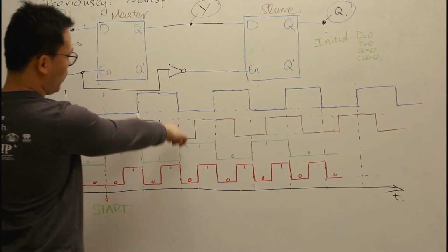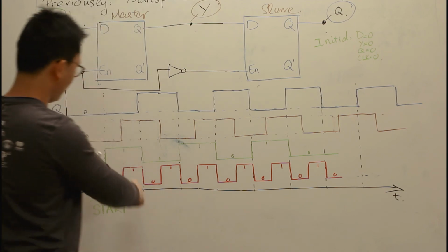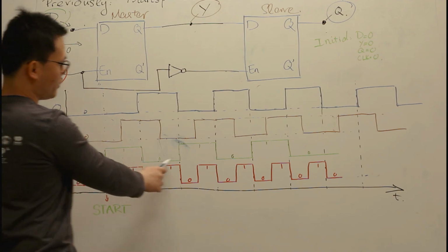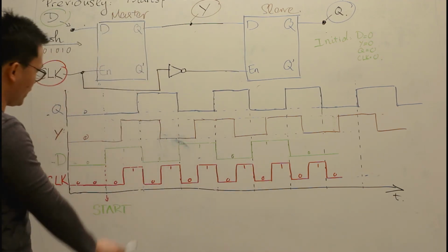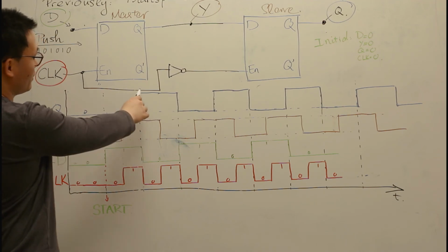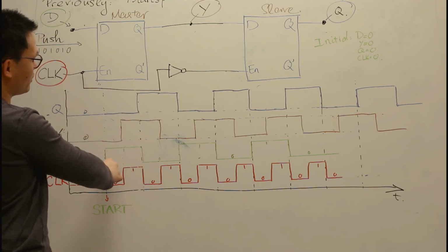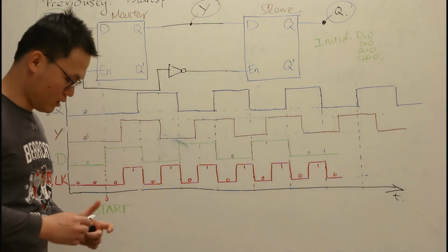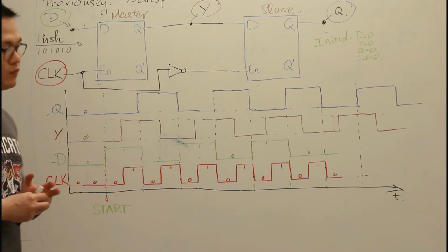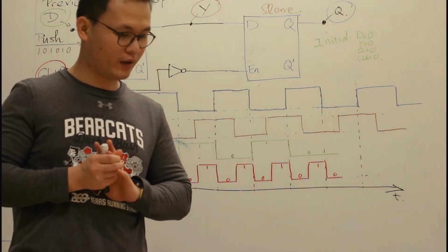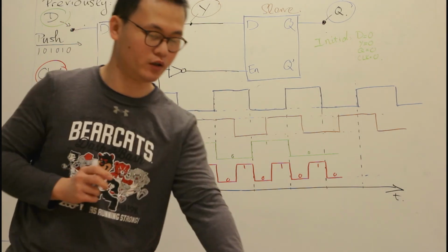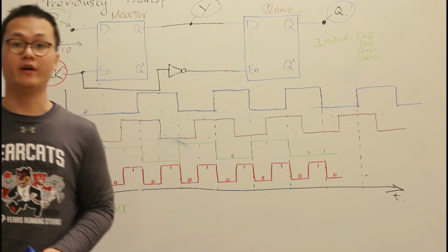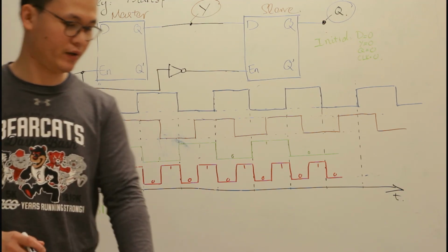And you can see in here, each frame is one clock cycle, right? And my series is 1 0 1 0 1 0 and so on. You can see that the 1 0 series doesn't start until one clock cycle after I change the input of D. So you can conclude that the delay of your D flip-flop is one clock cycle, or one clock period. This will help with your design later.